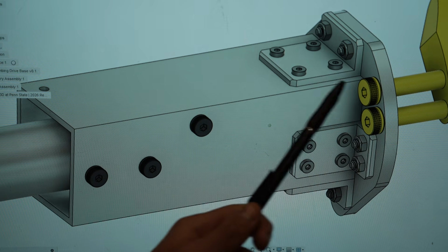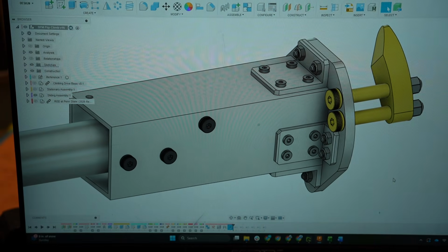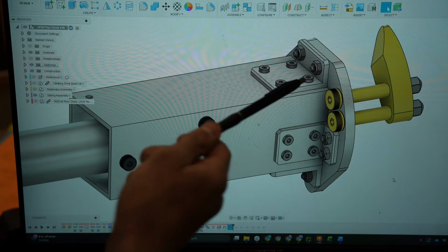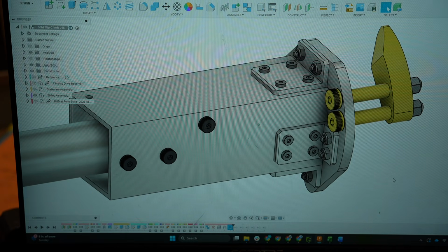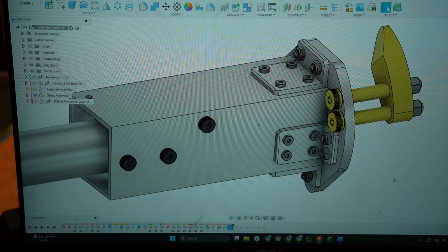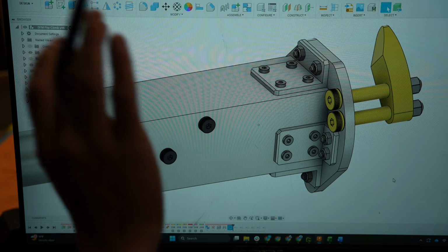The right angle brackets are a little difficult to do analytically. So we're going to run them in FEA. When things are weird shapes and not long or beam-like, it becomes tough to analyze them because you get weird combined loads. FEA is finite element analysis, and it's breaking this down into a mesh of a bunch of little points, and then the computer can solve it for you. But definitely almost always possible to bound even a complicated shape with hand calc analysis on both sides, which is what Jonah's doing now. So we could, but we're not.